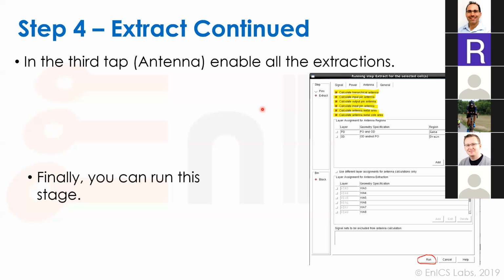Beyond that, there are some grids for these layers. It's not a must, okay, because I understand that when you do a layout for a memory, for example, you cannot assign the pins on some grid because it's a replicated array. But sometimes if you have some wrapper and there are digital pins, it's better to prepare them aligned, because the job for the router will be easier and less probability for future DRCs and stuff.